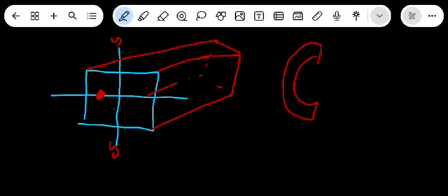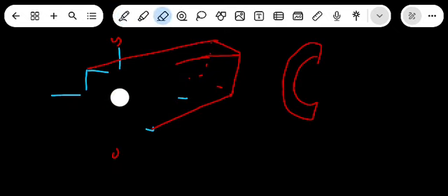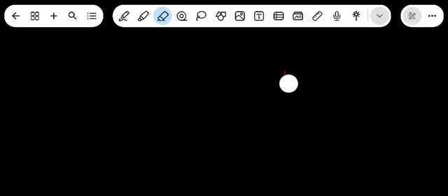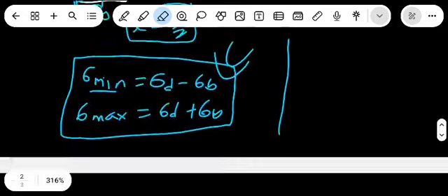That is what you're supposed to know again. And then remember where the force is applied here. Remember this distance will always be, as a trick, the distance from the center until where the force is applied. Even if it's applied here, it will be the distance from the center until where the force is applied. Here is our center, and this line will be the distance until there. That is e. So you'll choose the e depending on whether it's bending in the x-axis or the y-axis. I will do some examples in the next coming session.